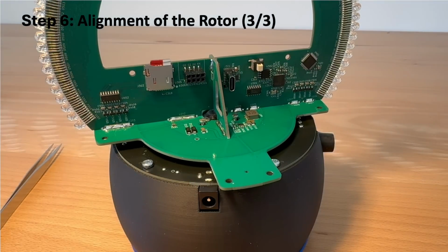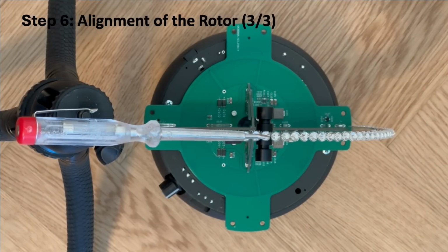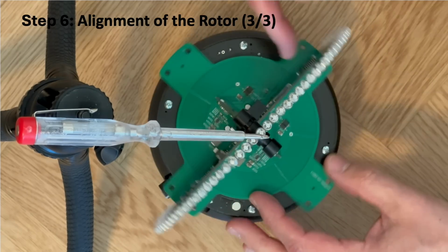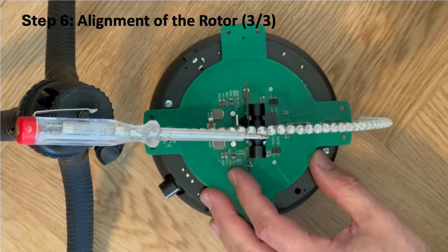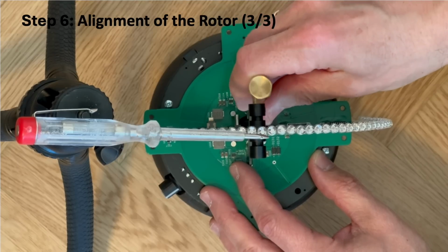The next step is to adjust the alpha angle. To do this, a pointer is placed above the display. I use a screwdriver held in position with a tripod. By rotating the display 180 degrees, you can see the misalignment. The misalignment is then corrected using the adjustment screws.